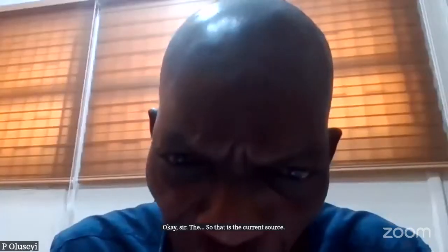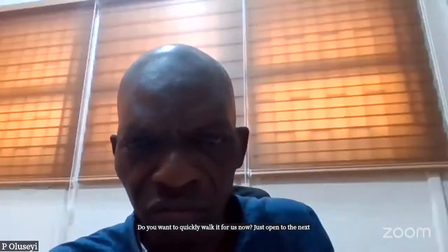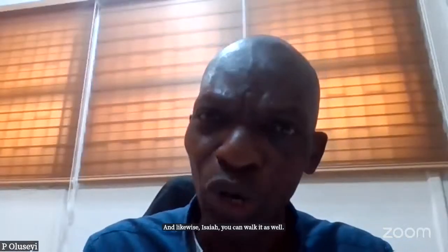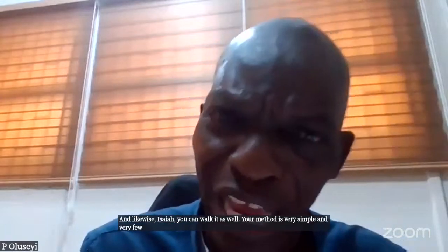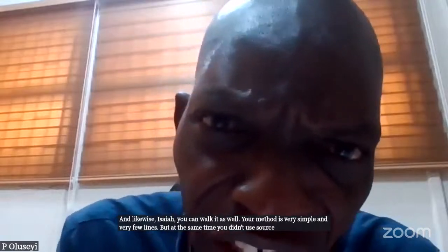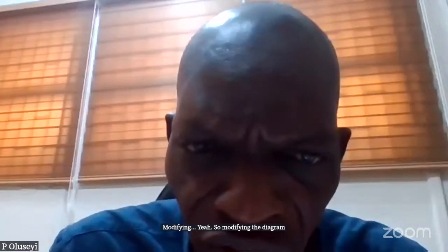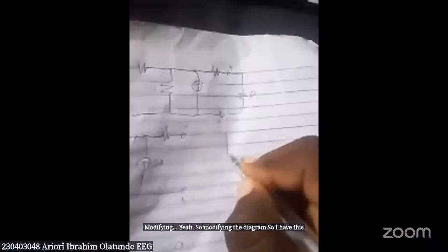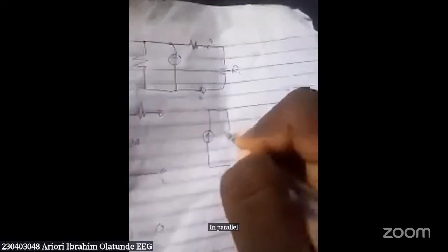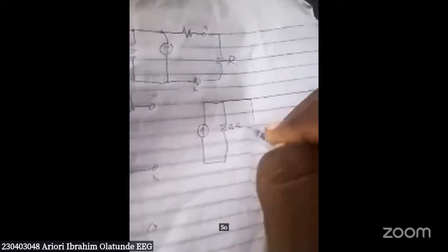Do you want to quickly work it for us now? Okay, sir. Just open to the next page and work it. And likewise, Isaiah, you can work it as well. Your own method is very simple and very few lines, but at the same time, you didn't use source transformation. Isaiah, do you agree with me? Yes. So modifying the diagram, I have this in parallel with the resistor, which is 4 ohms, and also in parallel with 12 ohms.